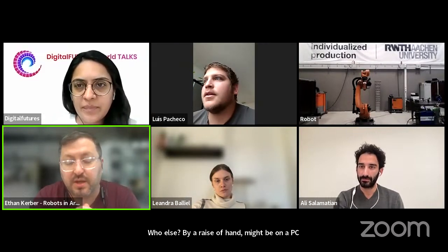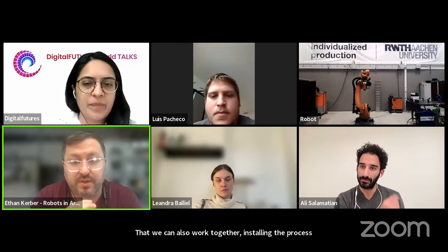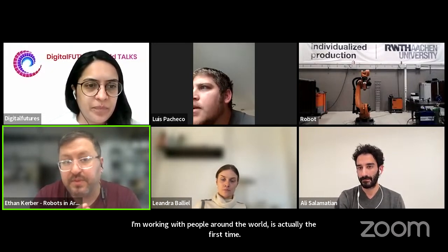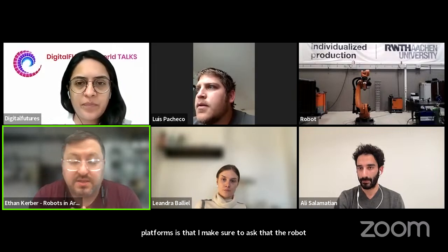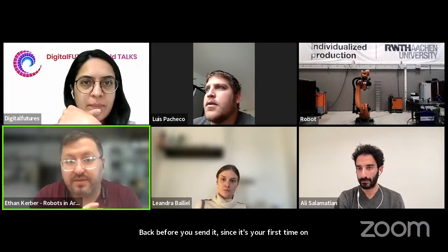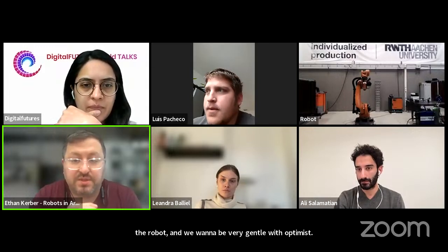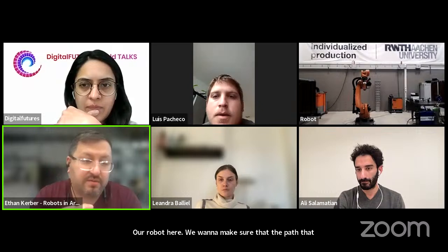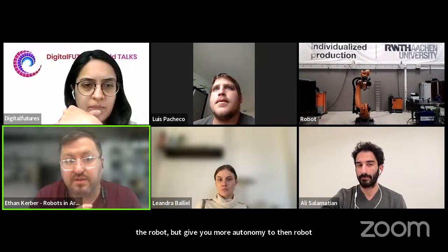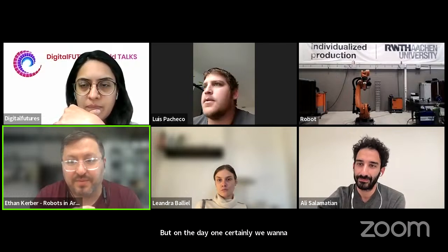Yes, I am. Who else, by a raise of hand, might be on a PC that we can also work to get installed and controlling? The process with KUKA-CRC, when I'm working with people around the world, is that I make sure to ask that the robot path is simulated for me to inspect before you send it. Since it's your first time on the robot and we want to be very gentle with Optimus, our robot here, we want to make sure that the path you're about to send has been inspected and approved. Normally, if you got more advanced, we would certainly oversee the robot, but give you more autonomy to send robot commands without a deep dive into each and every little plane that you're sending. But on day one, certainly, we want to work closely together with you.